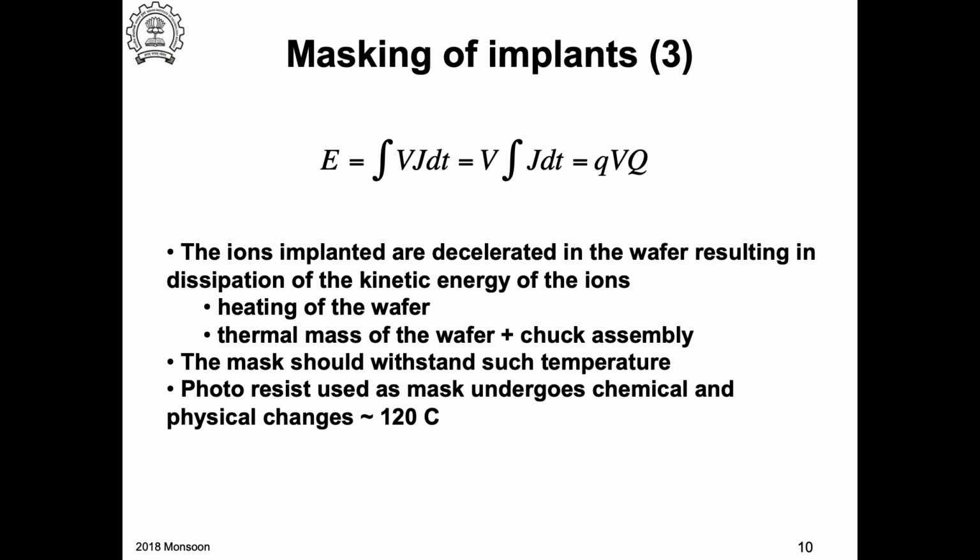But you should keep this in mind that when you're doing implantation, the implantation is not just used for this purpose, it is used for many other applications as well. So if the materials that you're dealing with are sensitive to low temperature, they are not like silicon, meaning silicon also gets damaged during the implantation, but you can recover. In this soft material, the recovery may not be possible. Or you may actually end up with some difficulties.